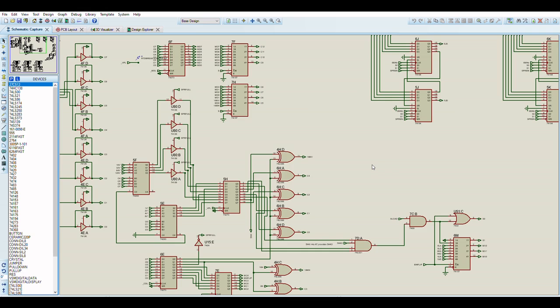It decides on whether or not the sprite data buffer scan line logic needs to be activated or not for this particular sprite, based on this adding, inverted subtraction, if you like, from this test here. This is why it was really simple and not much extra work to put in a whole bunch of extra functionality for using full screen sprites, for example.